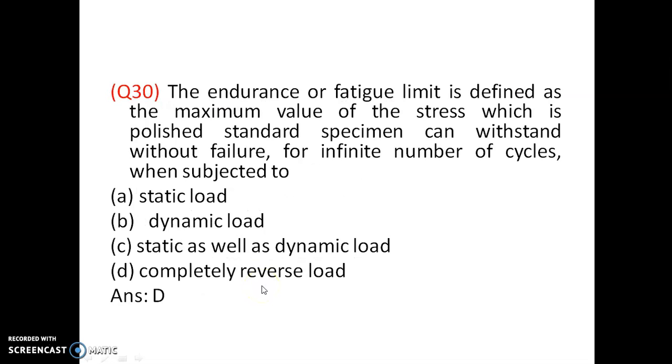Option is D. The endurance or fatigue limit is defined as the maximum value of stress which a polished standard specimen can withstand without failure for an infinite number of cycles when subjected to a completely reversed load, tensile and compressive. Not a static load, not a dynamic load, not static as well as dynamic load, it is a completely reversed load, tension and compression. Okay, so the option is D. Endurance or fatigue limit is the maximum value of stress which a polished specimen can withstand without failure for an infinite number of cycles.